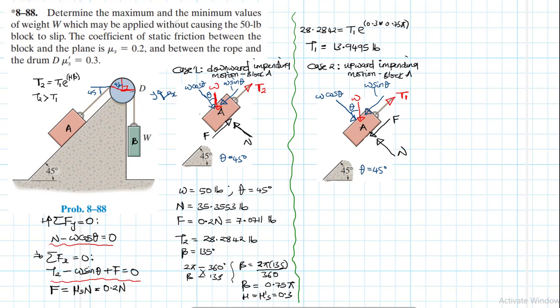So what we just need to do now is to apply the equations of equilibrium quickly. So we have summation of forces in the y equal to 0, going up being our reference, and this is our coordinate. It's inclined. This is x positive, this is y positive. So in the y direction, we have minus W cos theta plus N equal to 0.